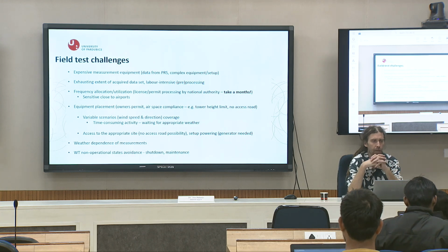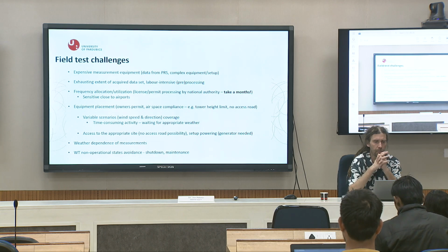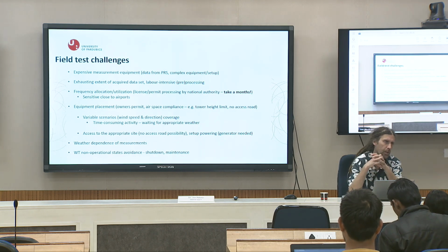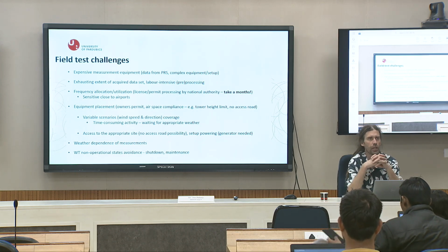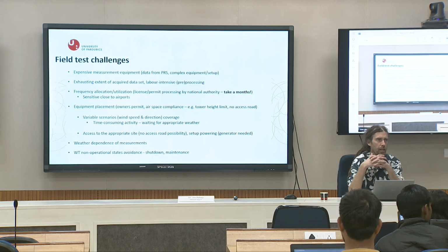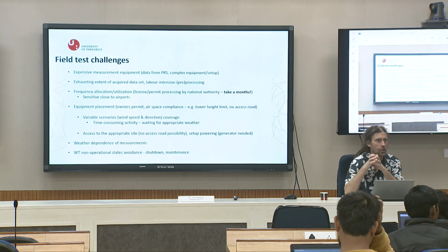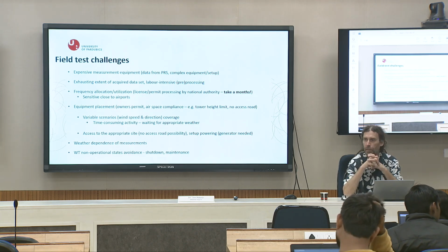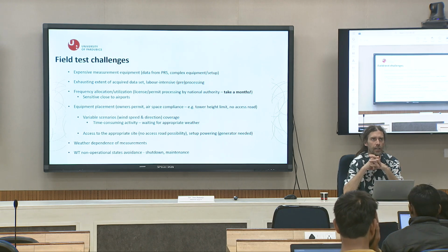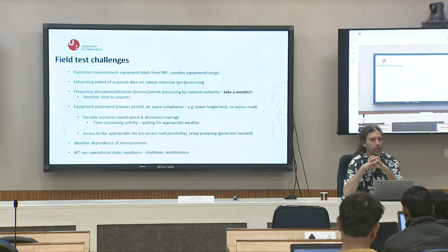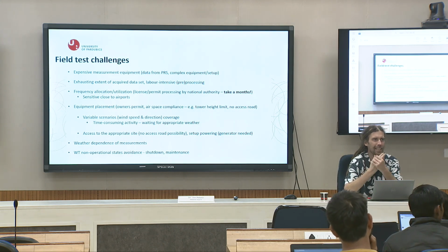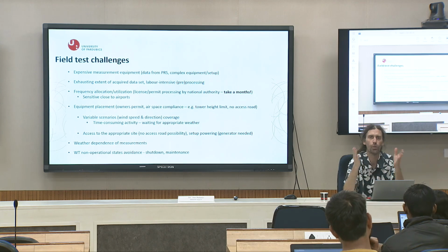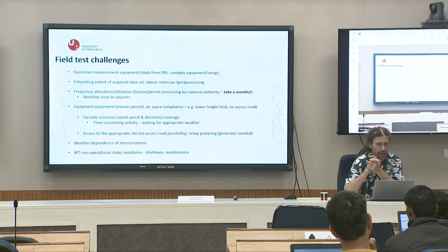Also, before measurement, we need to do frequency allocation and utilization, and getting a license or permit processed by the national authority could take a month. It of course depends on the individual country, but generally getting this license is not so easy. Especially if you are in an area that is protected, like airports, close to a nuclear power plant, or some important object, if you get my point. So of course transmission around this area or close to borders can be relatively tricky.